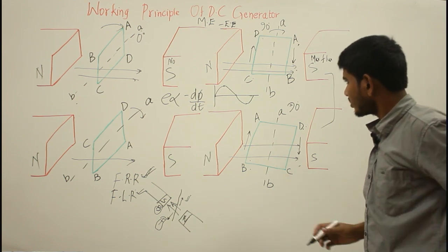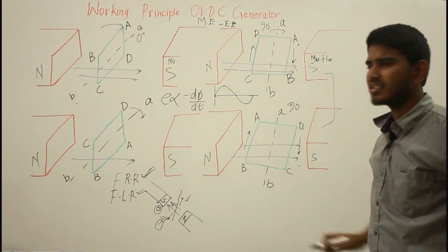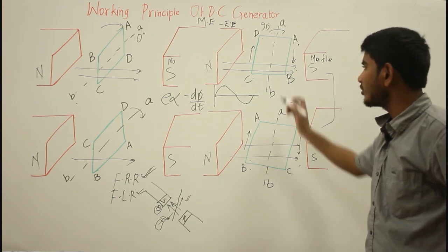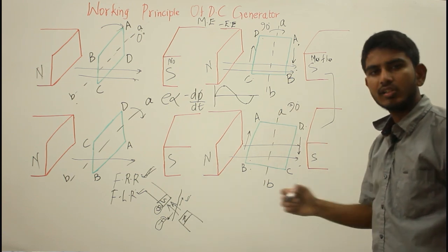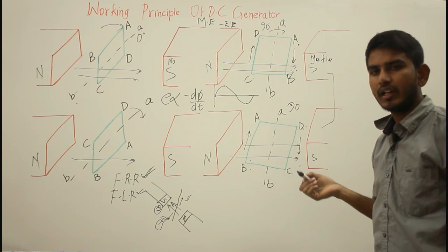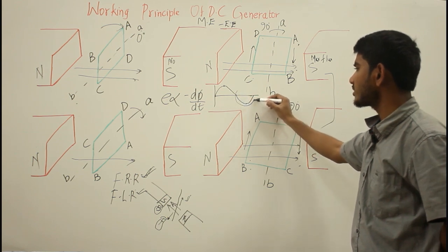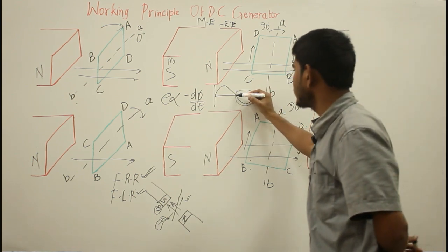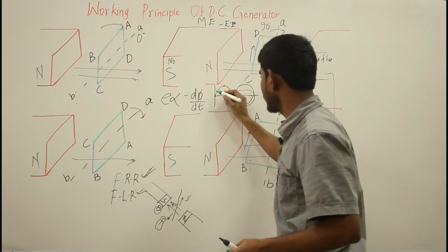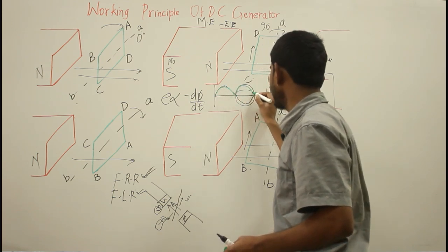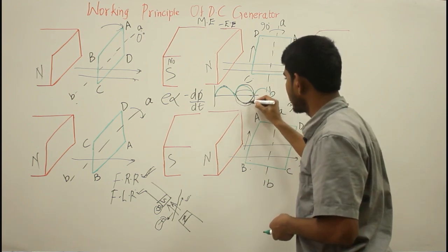So how can we use this alternating current to generate the DC output? Normally in AC generators we use slip rings. Here we connect two slip rings, and the brushes riding on the slip rings are connected to the load terminals, and you can see the alternating current in the load circuit. But to convert this reversing current to direct current, the basic output I need is in this form. So this current has to be reversed.